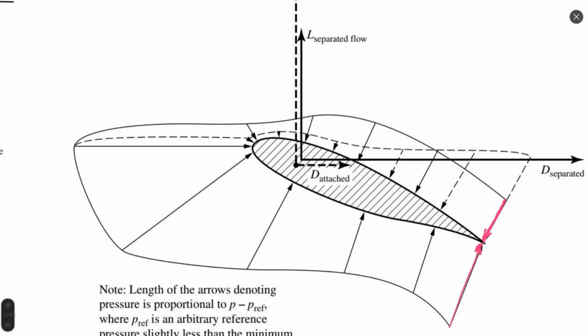And these two points are very close to one another, since pressure gradient is a source of flow movement. Pressure gradient is extremely high. This is why flow from one region to another happens: because points are close, pressure difference is significant, pressure gradient is high, small flow separation starts. Everything starts from small and then increases with the increase of angle of attack.